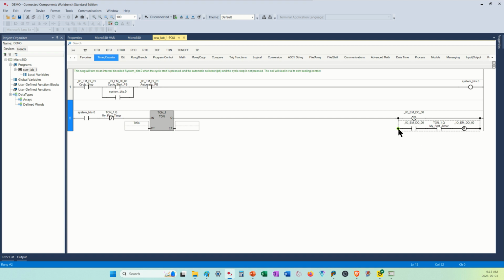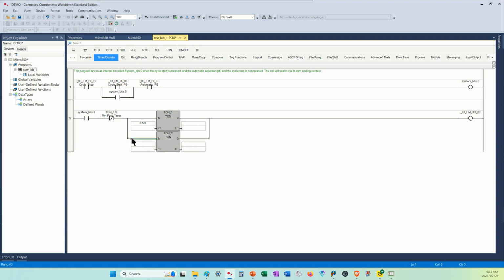Now, when you delete a branch, be careful where you highlight it, beginning and end. Take the end and press the delete key. Poof, there it is gone. I'm going to go back and make this an output. And here's the standard selector. And I'm going to play Mr. Smarty Pants again so I don't embarrass myself too much. Create. Put a second timer.